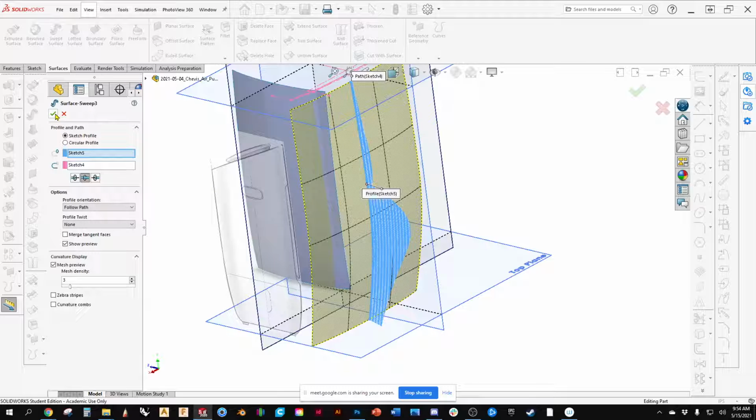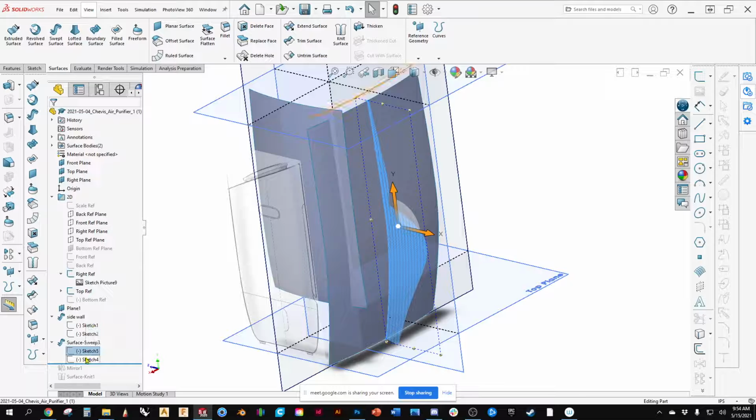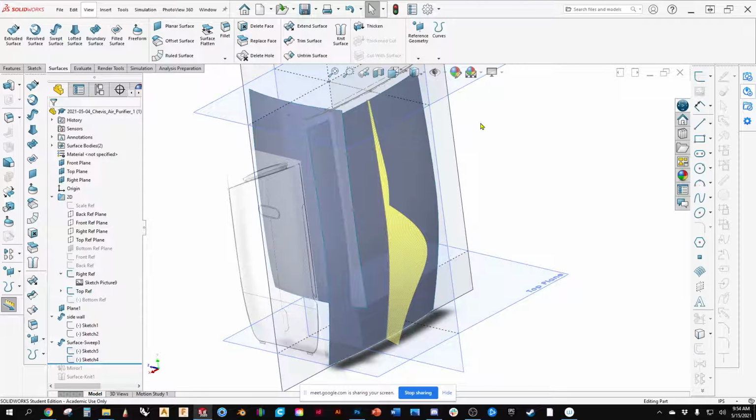Now, as I was talking, let's turn on our surface. Quick question, sorry. Is it ever acceptable to have isoparms that aren't evenly distributed? Because I know sometimes in Rhino, the only way you can rebuild it, it will be less even. Yeah. So the textbook answer is no, your isoparms should always be perfectly clean.